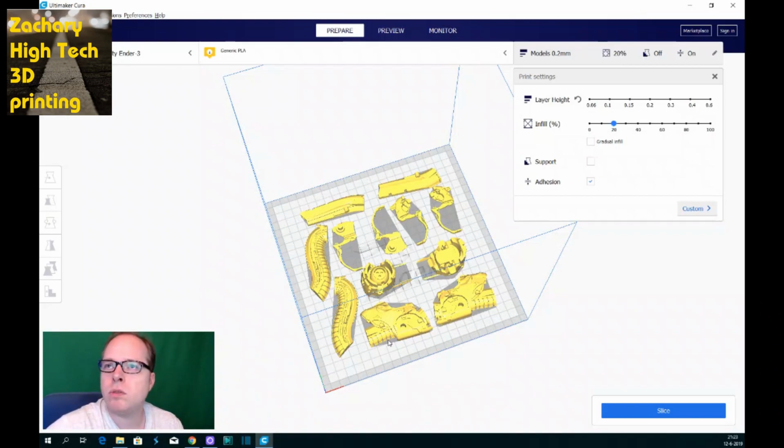And now we're going to use some settings. Well, I've got it on models, so that means 0.2 millimeters, 20% infill. The instruction says just 10% will be enough. Also, support is off. Well, no support really needed because everything is laying flat, and it's on the building plate, so that means no rafts, just like in the description in the readme file. So this is all set.